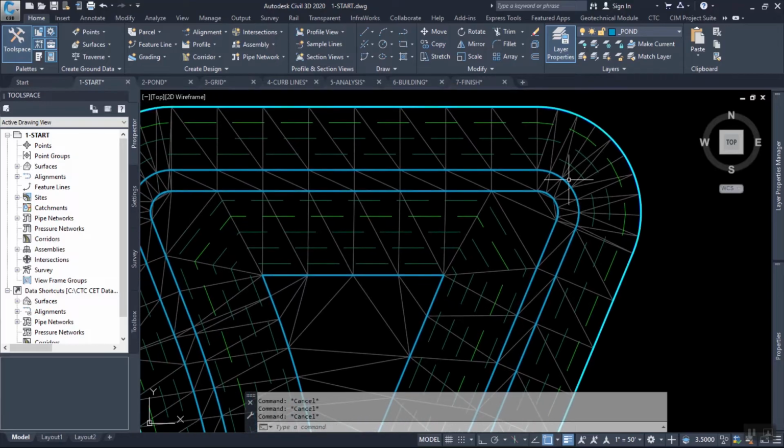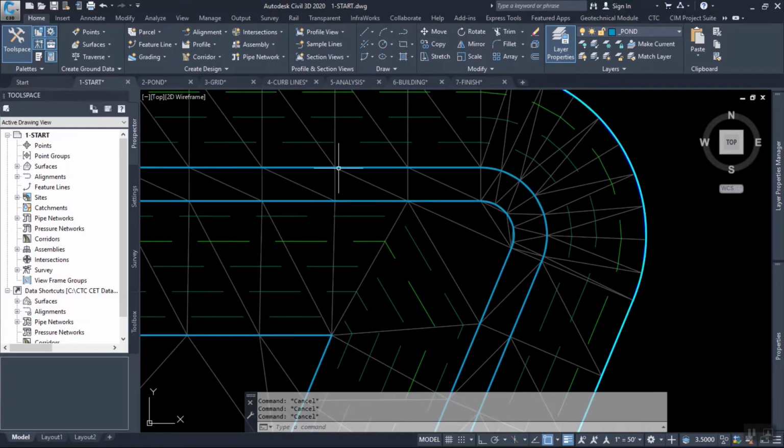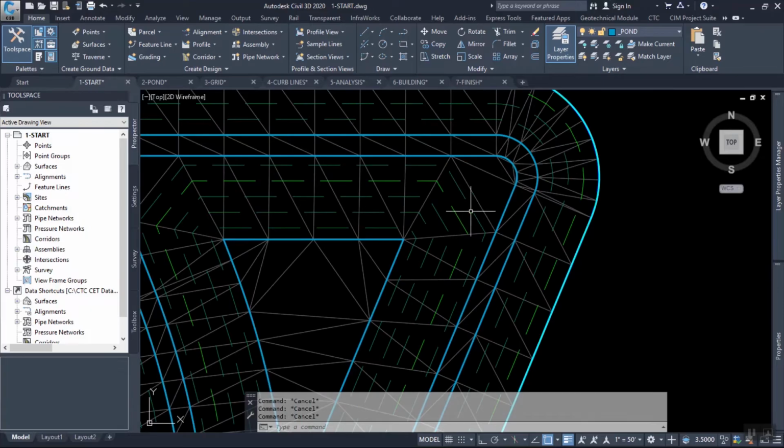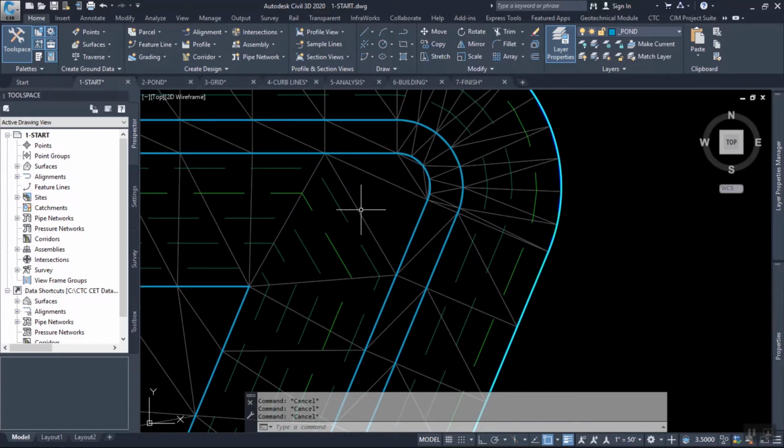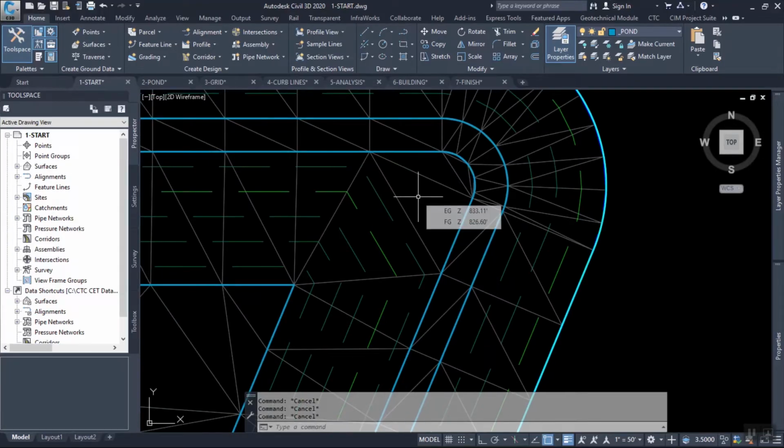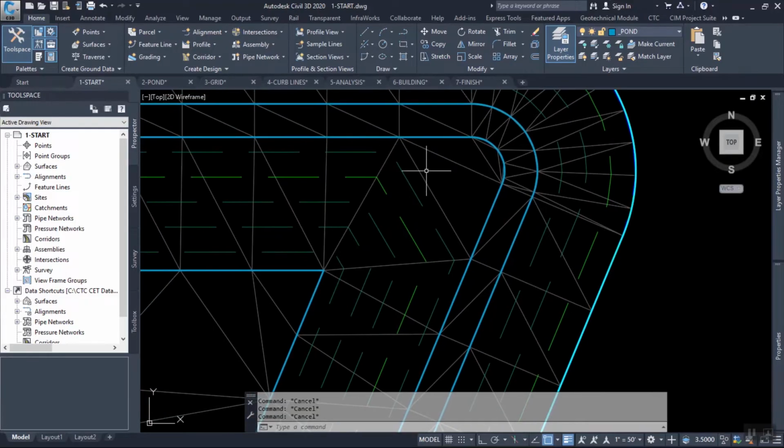We talked about how things triangulate, right? This looks like pretty decent triangulation, right? Enough to get the right detail. Contours are decent, but it's not like a bazillion triangles, so my drawing turns into 100 megs. But then your surface will start to do stupid things like this. Why is it doing that? And what would you normally do? Swap the edge, right? Okay, avoid all that, like what I call Band-Aid fixes to it. Don't swap the edge. Understand how this is behaving. These triangles connect to the nearest, so to speak, the nearest vertex that they can, right? So really what needs to happen is this line needs to go from here to there. Wouldn't a break line solve that?